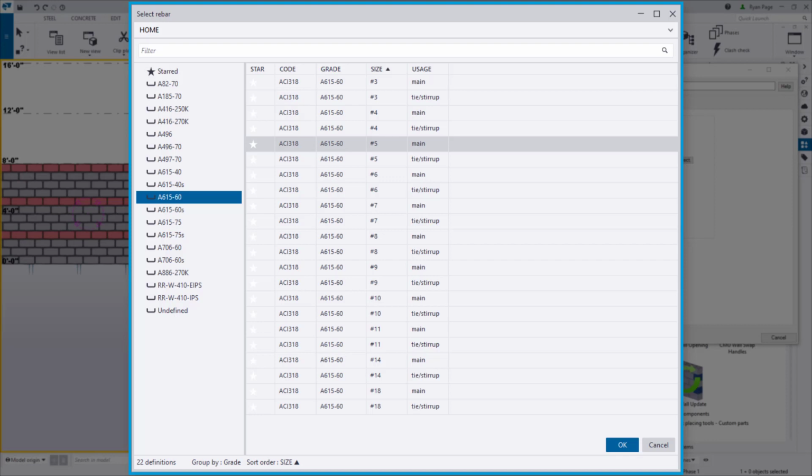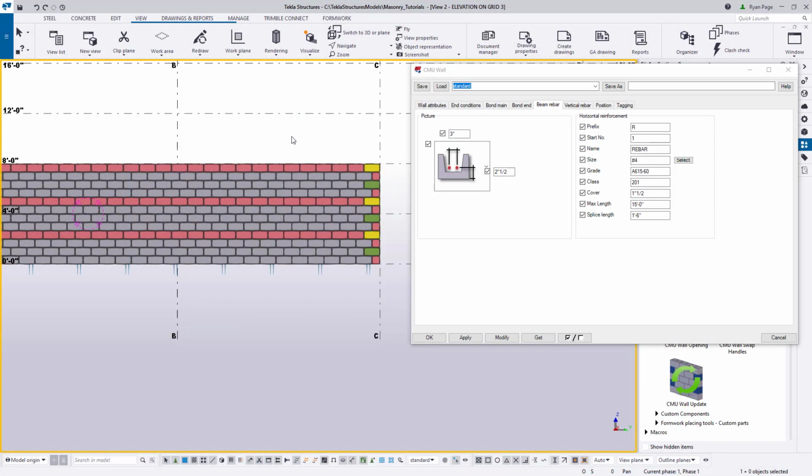As you're very much aware, the bending radius between main bar and then tie or a stirrup differs, so it's important to ensure that we're choosing the correct bar type, as we want it to be as accurate as possible to real-world conditions and fabrication needs. This is why the best practice in selecting bar size and material grade is to open up the catalog and select it, as opposed to typing in the field itself. This way, you ensure that you're getting exactly what you need.